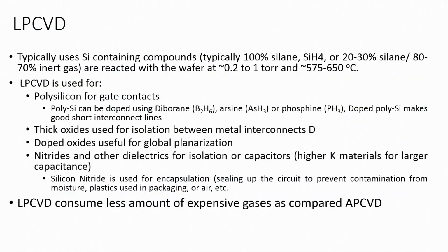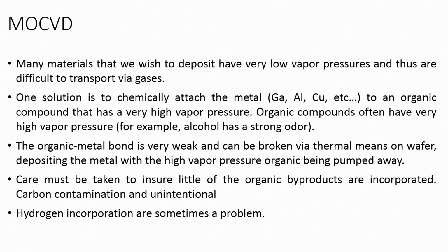So, in the next module we will see surface plus bulk micromachining, and we will also see this novel technique, plus we will see how different actuators are fabricated, how cantilevers are fabricated, what a DRI structure is, and how wet versus dry etching can be compared. Thin film deposition, we will see CVD techniques, 4 basic types such as ALD, PECVD, LPCVD and metal oxide, and then we will also see MOCVD. So, this is what we will do.